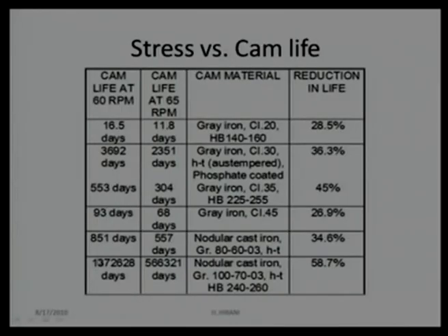It is a dynamic process. If the micron level particles have been removed from the surface, clearance will continuously increase. If the clearance is continuously increasing, impact loading will continuously increase, and that may cause more problems. So, this will be totally hypothetical, and I am saying that in this case we are just considering only pitting failure. We are not assuming any other kind of failure. We are not talking about the abrasive failure, we are not talking about adhesive failure, or about change in dimension. If there is a change in dimension, increase in clearance, this life also will be reduced. Wear cannot provide that high life.